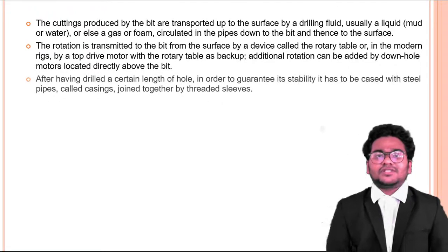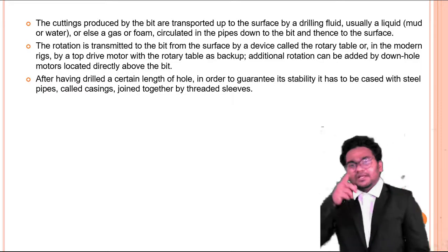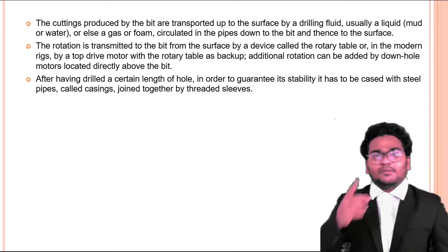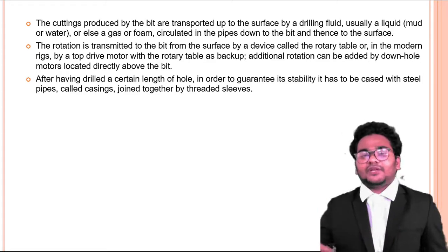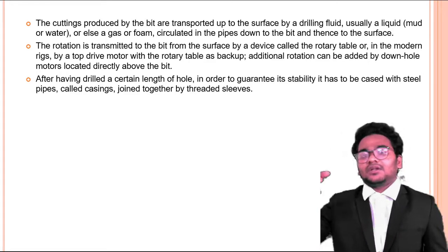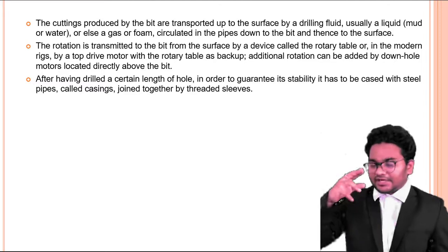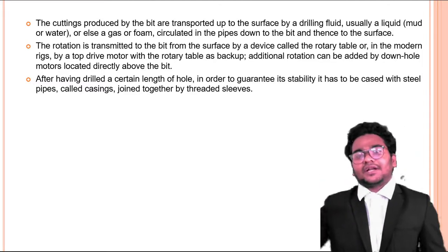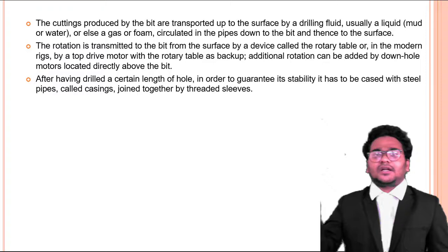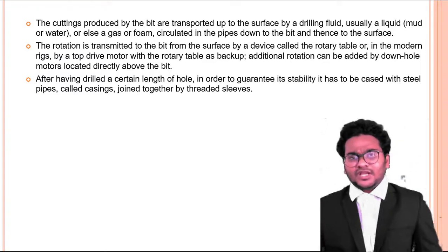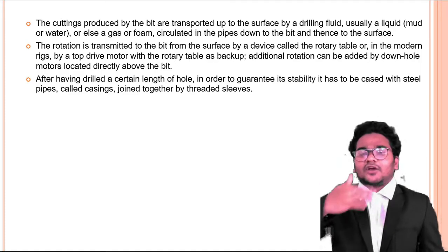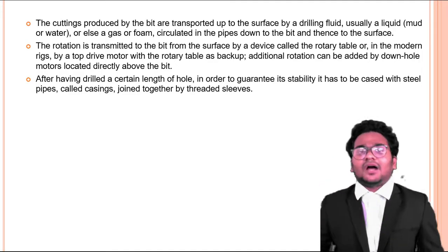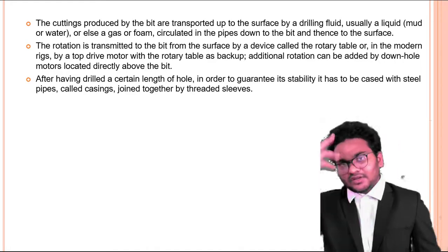So for the circulation of this drill fluid, we will use motors, pumps and everything, so that it will pump from one place to another place, and automatically the drill cuttings are taken out. Then the remaining cuttings which are coming with the mud will be taken out by using shale shakers, hydrocyclones, dehydrators, like that. We have different process equipment. According to that, we will remove all the cutting samples, and the fresh mud we will recycle. That will again be sent into the drill bit zone.